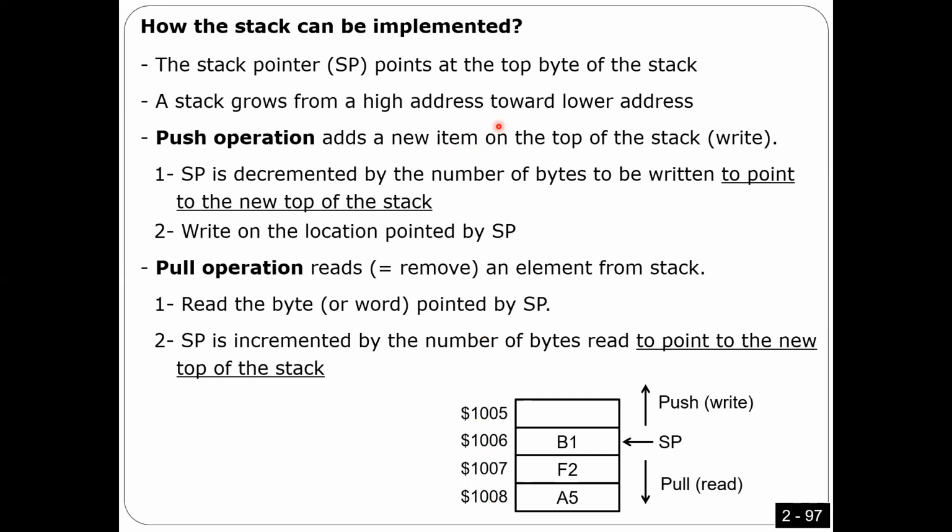But for our microcontroller, the stack is going to grow from big addresses to smaller addresses, and it's going to shrink every time you read something or pull. The stack pointer has to go this way, from big addresses to smaller addresses. Is that okay, guys? Conclusion, because it's already 4:20. Conclusion, very easy. Look here, guys.